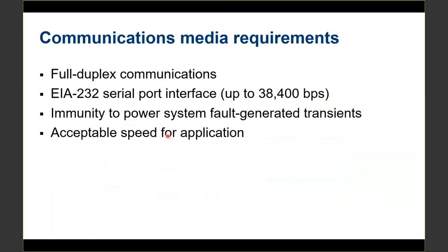The requirement for using the mirror bits protocol is basically a full duplex communication channel, because the messages are sent independently in both directions between devices at the same time. And most SEL mirror bits devices support communications of up to 38,400 bits per second on the 232 serial port.